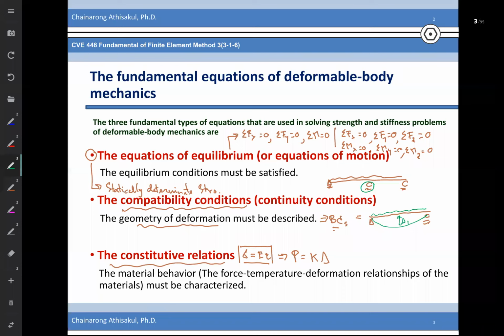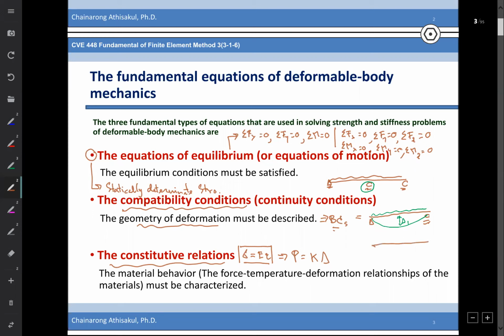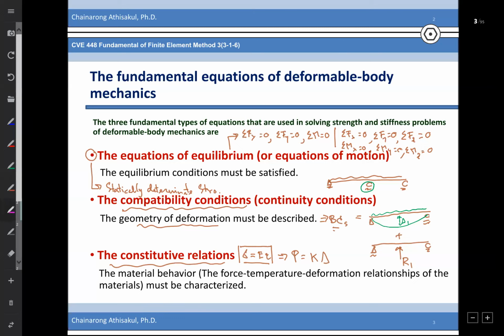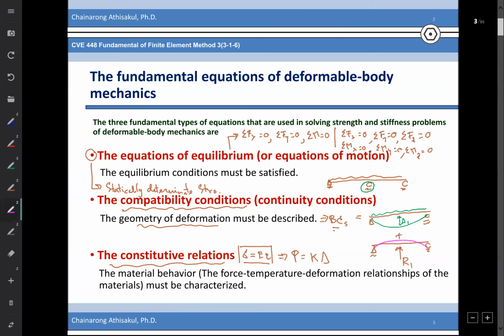Okay, and after you remove it, you have to add the beam that is subject to the load. That is, we change the reaction force of this support to be the redundant force R1. And according to this, it is the same, we have the deflection delta 2.